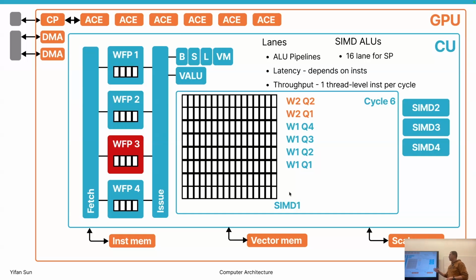The biggest failure of a design team is when you have one part that is super powerful, and the other part cannot catch up. Say your SIMD units are super powerful, but your memory is super slow. It's wasteful, right? You have a large die size, you have high cost, but eventually you can only render 1080p games. So perfect matching and keeping every part of the circuit busy is the art of computer architecture design.